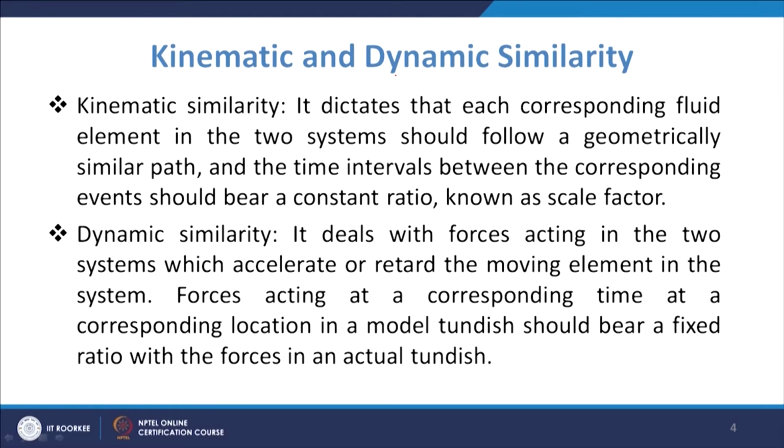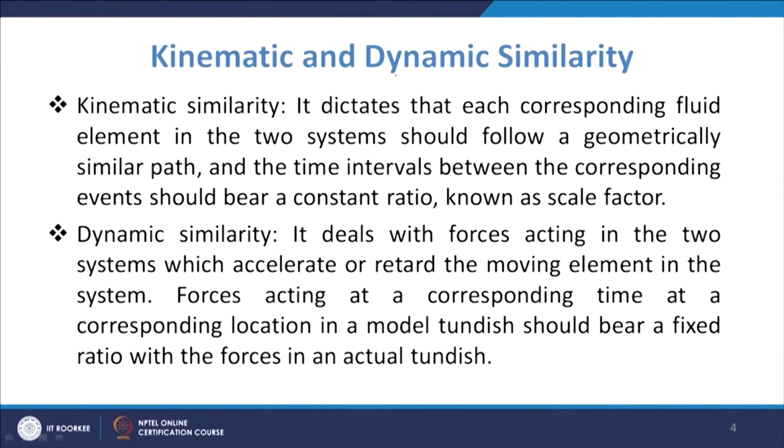As we talk about any system, you will have different kinds of forces acting inside the system, and forces acting at a corresponding time at a corresponding location in a model tundish should bear a fixed ratio with the forces in an actual tundish. So, this will be the dynamic similarity.